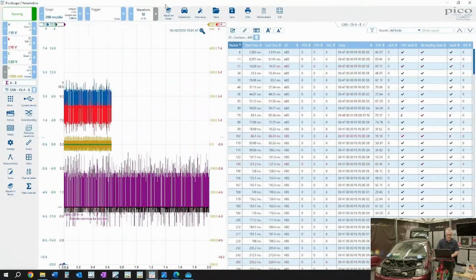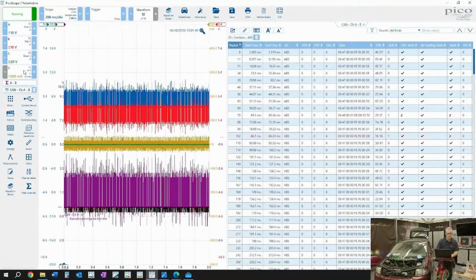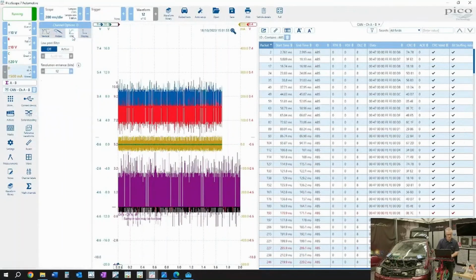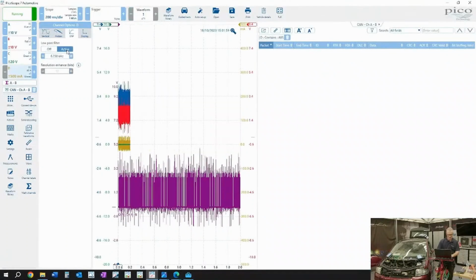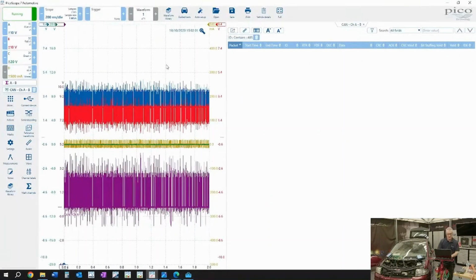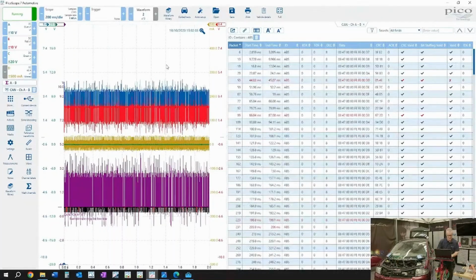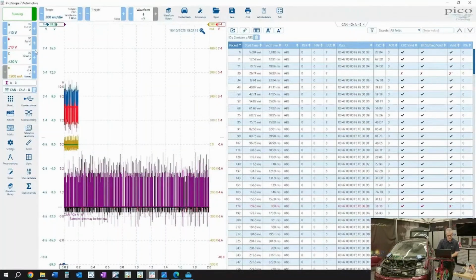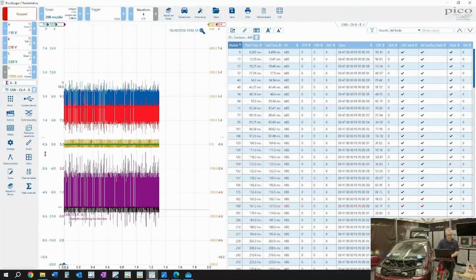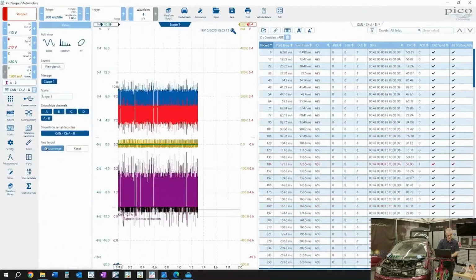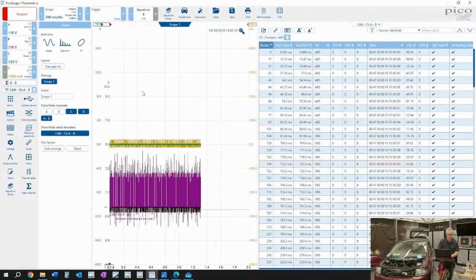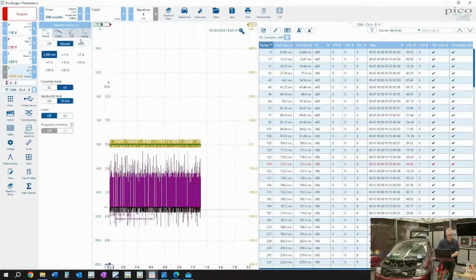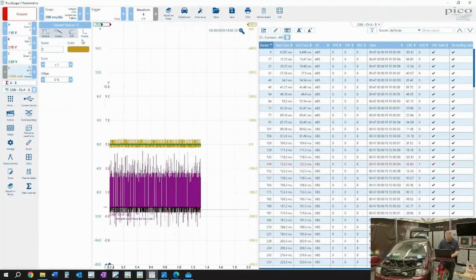We have to make some tweaks here because there is a lot of noise on this signal. So first of all, we are at 500 milliamp. We want to add some filtering, so we'll make the filtering active. So you'll see in a second that at the end of the buffer, notice how channel D just minimizes. In fact, let's clear this display up because we don't need to see a lot of what's on channel at the moment. Because we've got the math channel, we'll take away, using the views feature, channels A and B. They're still being captured, but we don't need them. The current clamp, we want to amend the scaling on there, and I think the scaling on this was something like times 10.